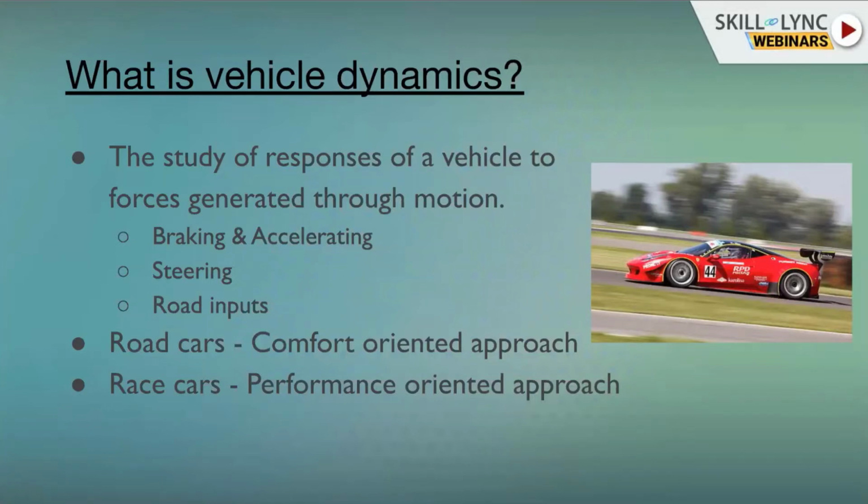Things like comfort, driver experience in terms of vibrations and ride comfort, that's completely not a focus in vehicle dynamics for race cars, and the approach is purely performance oriented. You're trying to maximize the accelerations that the vehicle can develop, both longitudinally and laterally.